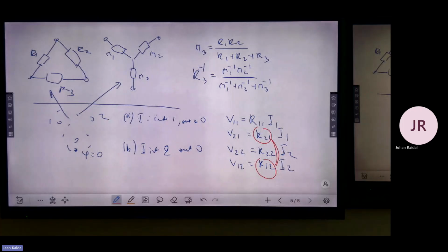As you can see here, an important component in using delta Y equivalence is actually the reciprocity. Without reciprocity, you wouldn't be sure it can be done, but now you are sure because the degrees of freedom for choosing delta or Y is 3, and here we have also only 3 parameters required to describe an arbitrary circuit.